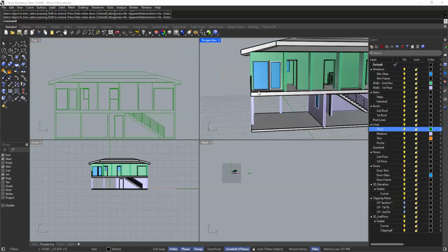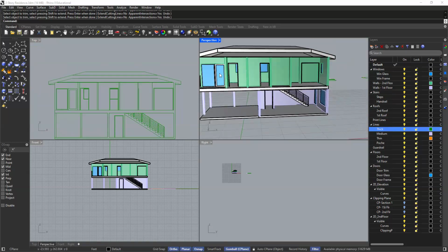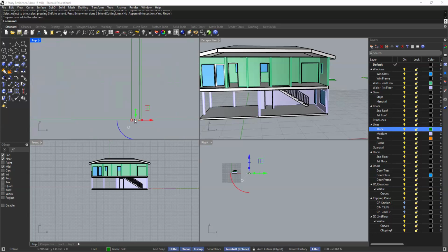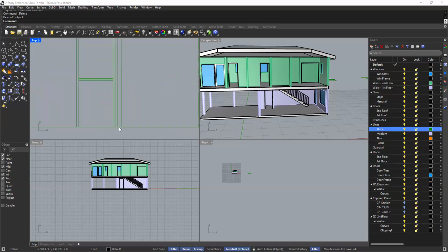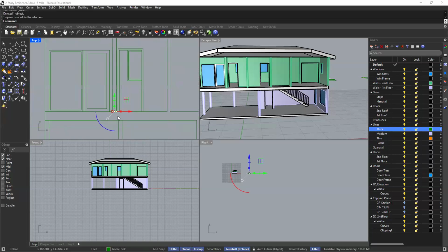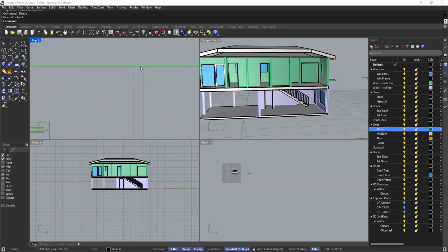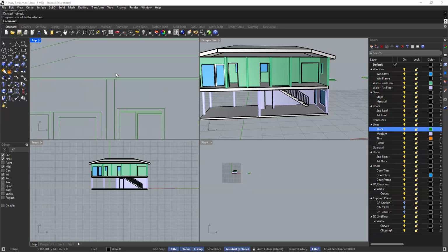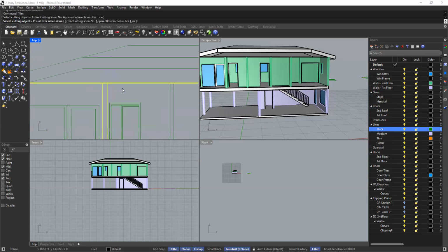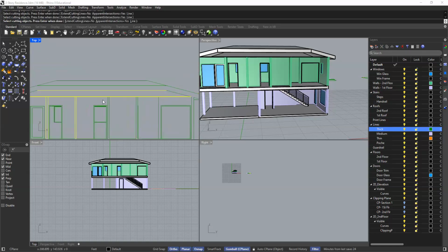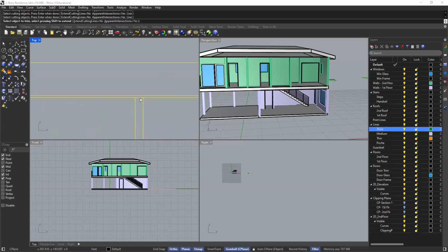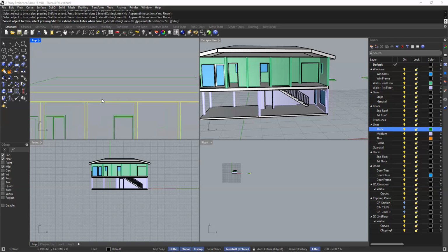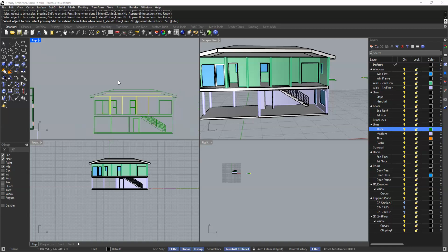And then in here, let's take a look. So yes, all of these walls here are going to get pocheted. So that means I need to delete these little lines. We could leave them, but it just means that it becomes an additional thing we have to click on when we do the poche. Is that correct? Yeah, okay. Now in here, let's hit trim command. Actually, I'm going to select all of these. Hit the space bar so then I can just go in and click, click, click, and click. Okay, that should be good enough.